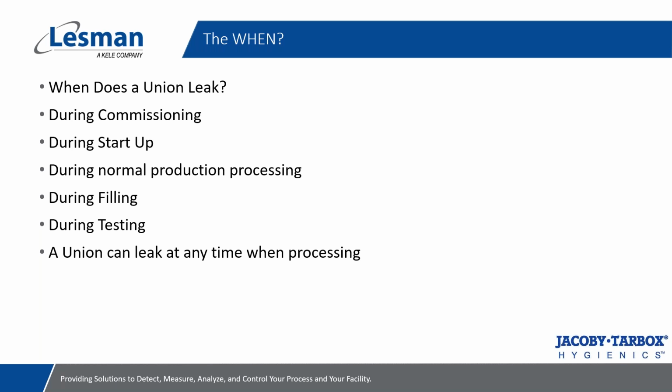Now, there are certain times that leaks become even more present or issues become more present. We hear very commonly from a lot of our customer base that they struggle during startup when thermal cycling starts to build. So as your process begins and things are heating up, or during a steam cycle for cleaning, that's when a lot of these unions kind of show their ugly side. And through thermal cycling, you get expansion and contraction, you get gasket creep, you get a lot of things that can contribute to the when will it start leaking.